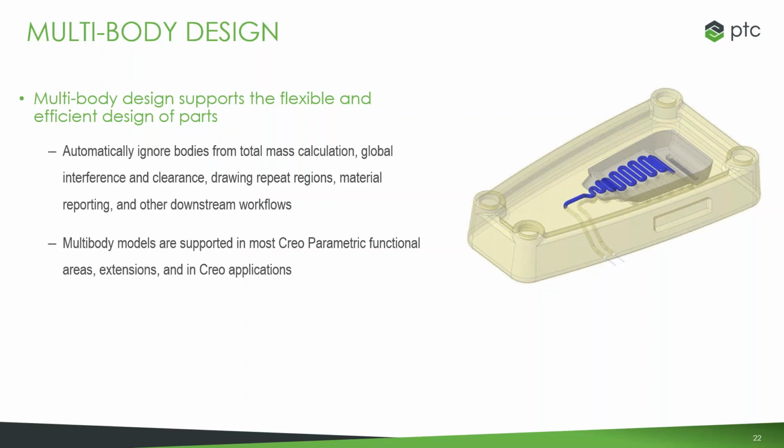You can then use them in different ways for your part and assembly generation, right? So if you're designing a part, maybe use a certain body as a construction volume, and then keep that out of the mass calculation, if you aren't going to include them in the final. You can have bodies interact, so define features or patterns as a solid body, and then add it or subtract it or merge it with other bodies to create the part geometry that you're looking for.